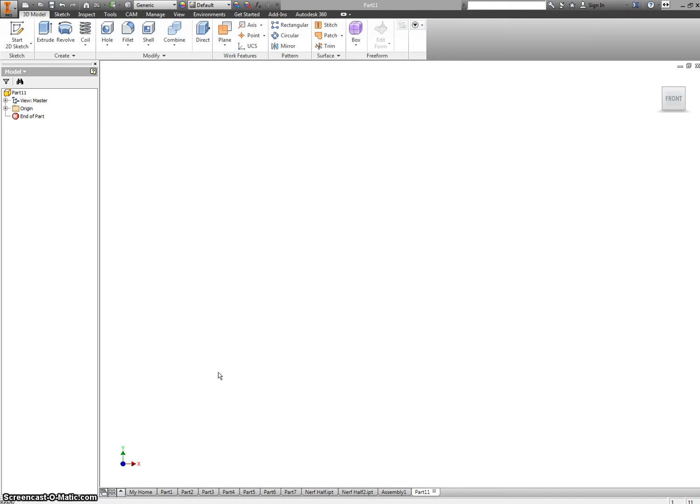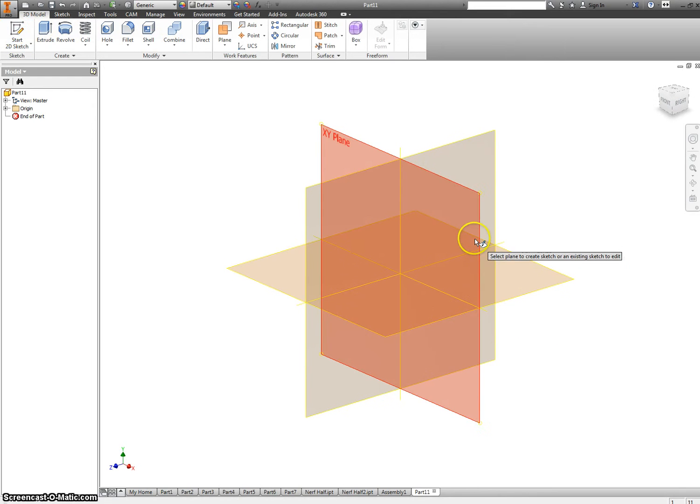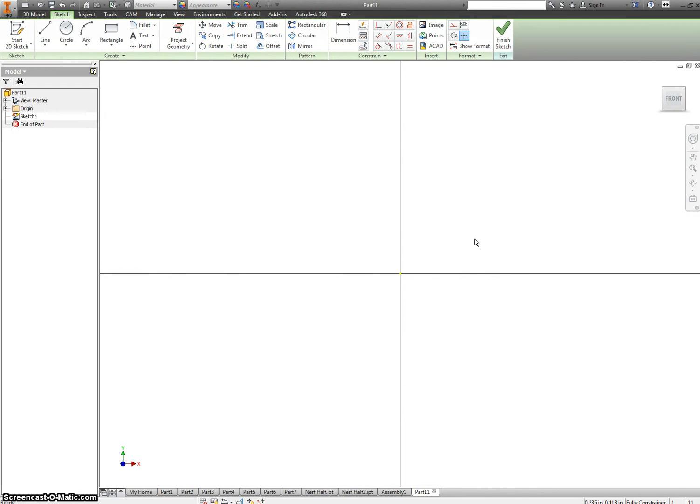Okay, this is for Jaden. Jaden is trying to make the coil inside of a tape measure, and this is actually fairly easy to do. It's going to be a lot like a regular spring, but instead of using a circle, we're going to use a rectangle. I'm going to make the rectangle's midpoint aligned with the midpoint here, and I also want to say